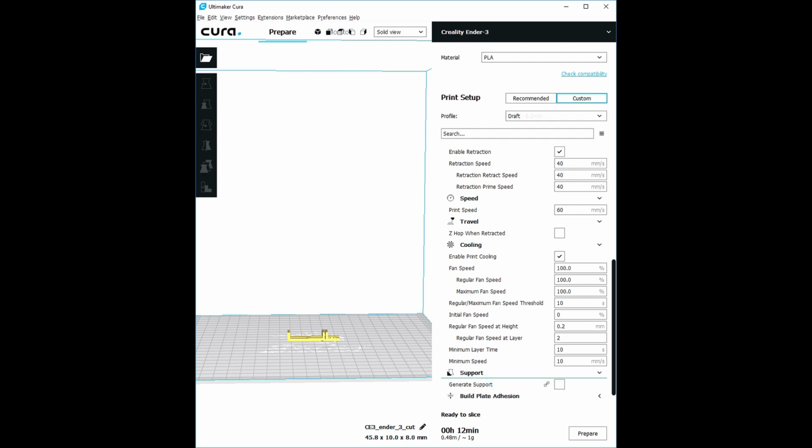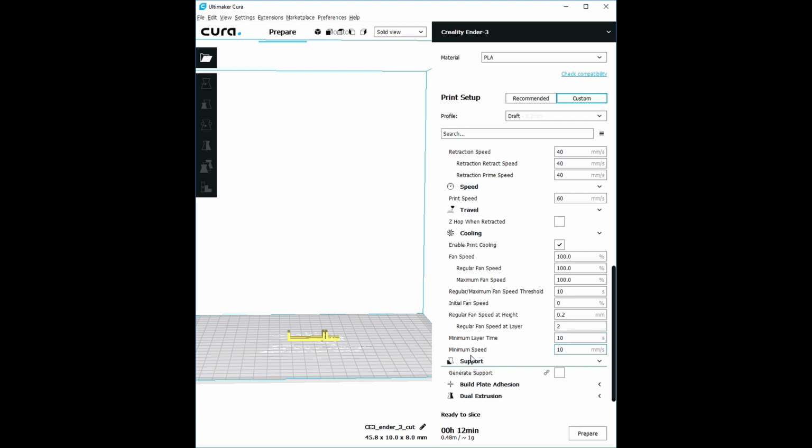The next thing is support. Support prints waste material that will not bond to the primary model. When there are areas that are printing above the initial height and need to be supported till the section bonds with a kept part. In other words, what that does is it prints supports. For instance, you have a big overhang and the printer usually doesn't print in thin air, so it'll print supports up to hold that part underneath, and then you'll end up taking those off later and throwing them away.